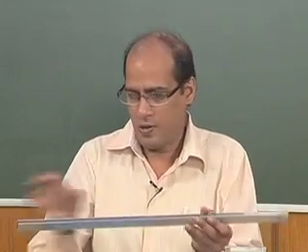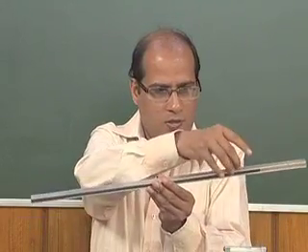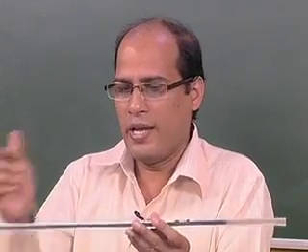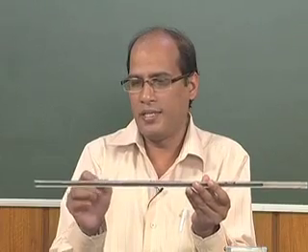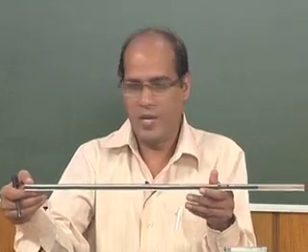So, here we have added a rubber patch in the aluminum. So, these are two skins, and between the two skins we have added the mass. This is a rubber mass, made up of viscoelastic material. So, this is a sandwich beam where the core is made up of rubber and the skins are made up of aluminum. Similarly, you can modify this rubber or this viscoelastic material.